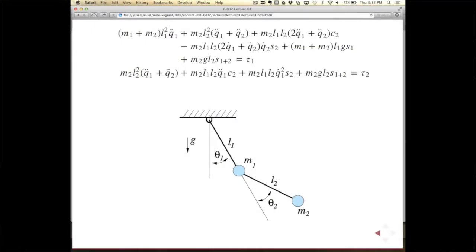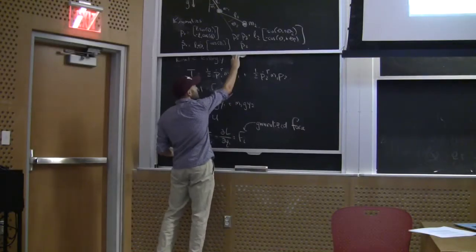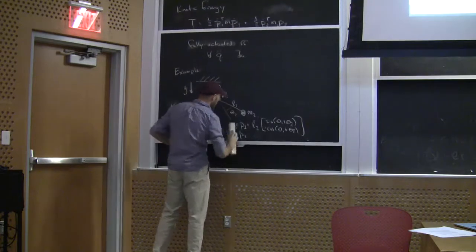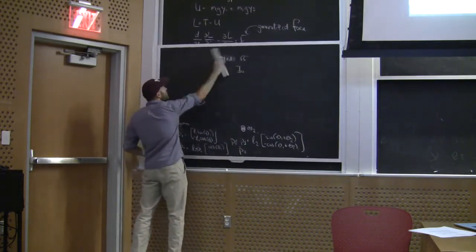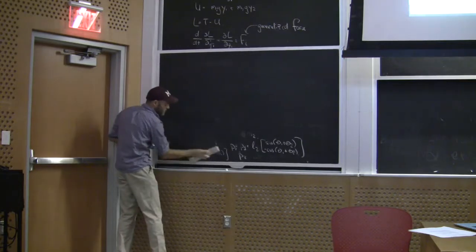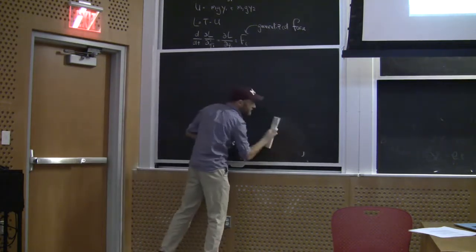So this is almost exactly in the form we've been using, q double dot equals something on the right-hand side. If you look, there are a couple of things you should notice. The torque is the input. The tau is my little u, my control input, tau 1 and tau 2. And you see the q double dots, q double dot 1, q double dot 2. If you write this down enough times for enough robots, you start to see some patterns emerge in those equations. And there's even more structure in the equations. It's not just control affine.